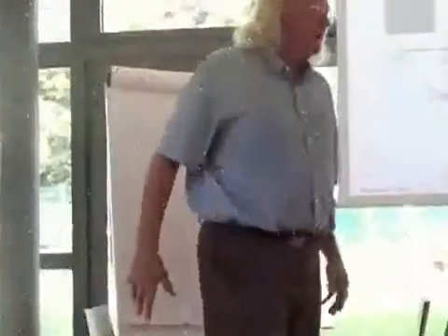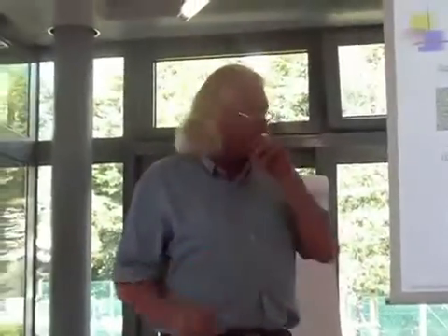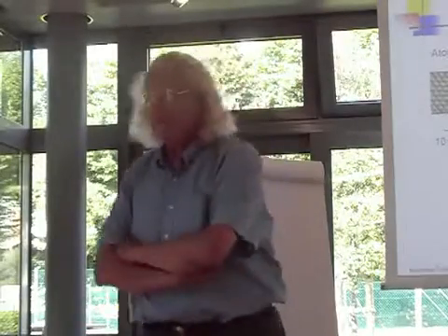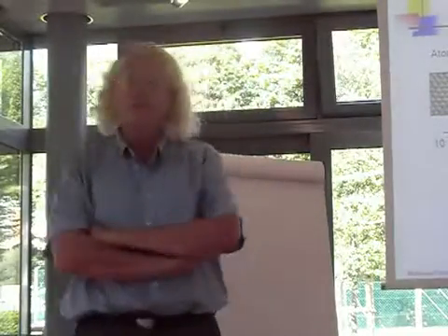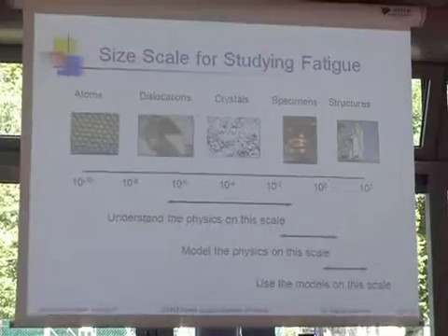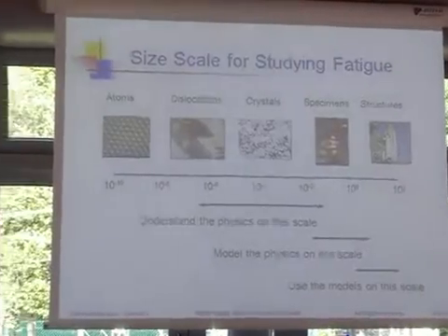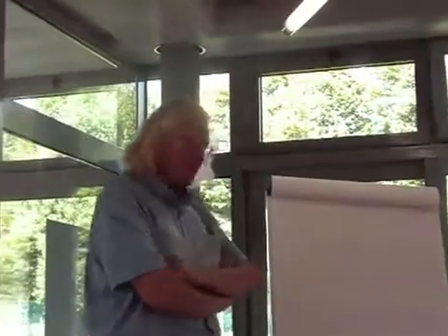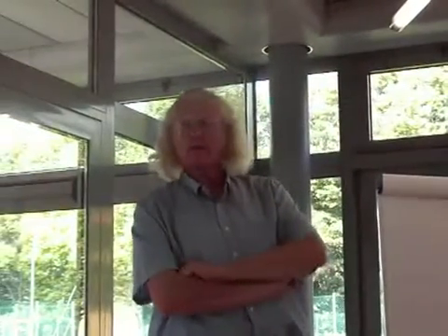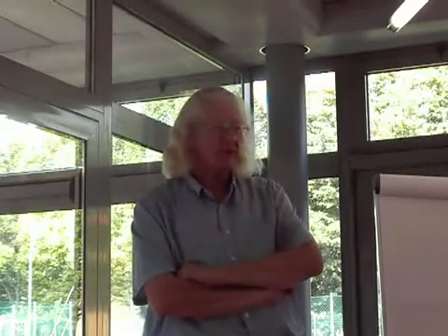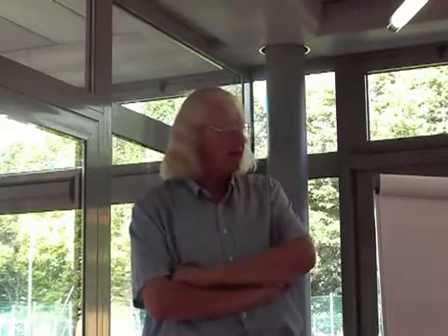So I now want to talk a little bit about the process of fatigue. And we can study fatigue on many different size scales, and of course people do. Starting at the atomic scale and then moving up, of course, to full-size structures. I like to think about the atomic scale because that's certainly where it begins. So fatigue happens because of plastic deformation, and plastic deformation is on that scale.